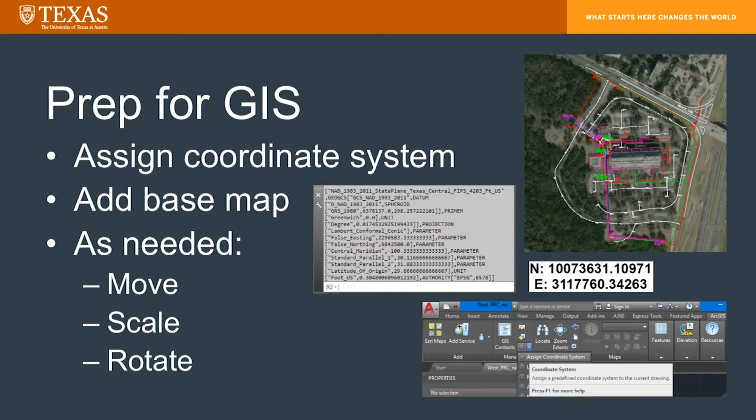Usually the ArcMap versions keep up to date, but we're using Arc 10.1 and 10.5.1, and we had to go all the way down to 2010, like Sue said. But with the newer versions, 10.6 and 10.7, you can probably get away with just leaving it in the AutoCAD 2018 version.